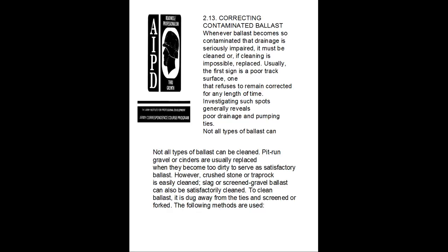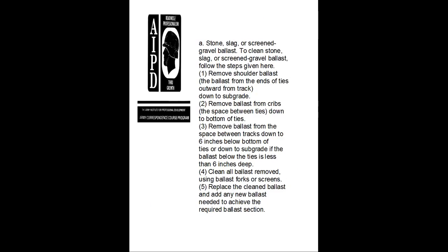Screen gravel ballast can also be satisfactorily cleaned. To clean it, the ballast is dug away, then screened with a tie screen and fork. The following methods are used. 1. Stone or slag screen gravel ballast. To clean stone or slag screen gravel ballast, follow the steps given.